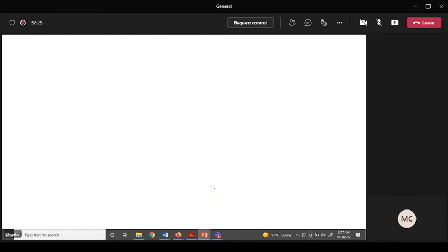I hope all of you know MOSFET. So MOSFET contains source. Say I'm talking about an n-channel MOSFET: source, drain, gate, and so on. So this is my gate oxide. Sorry, my drawing is not very good. You have to bear with me. So this is my gate oxide and maybe gate polysilicon. So this is your L, that is the channel length. There will be a channel between source and drain when you apply a certain voltage at the gate.